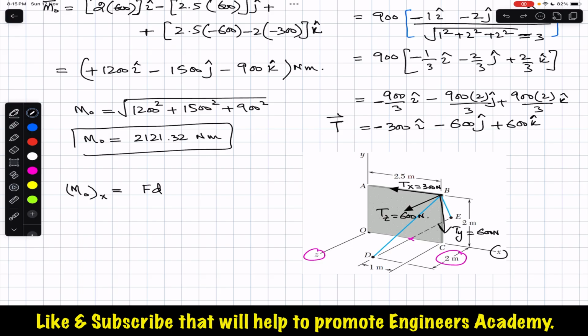So we can say that the moment at O about the x-axis is equal to Tz times the perpendicular distance between the Tz and the x-axis. The perpendicular distance between the Tz and the x-axis is this, which is 2 meters. So this is multiplied by 2. And Tz, we know that Tz is 600. So this is 600 into 2,